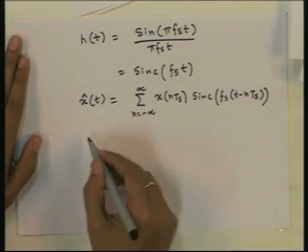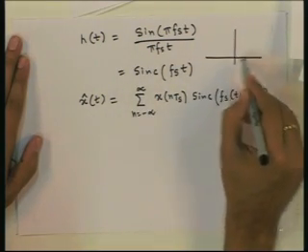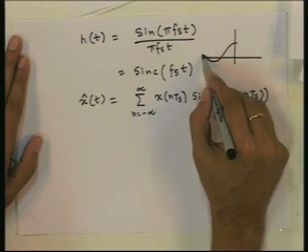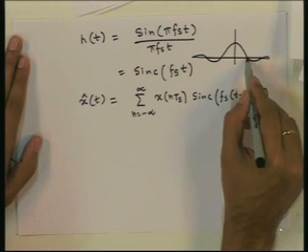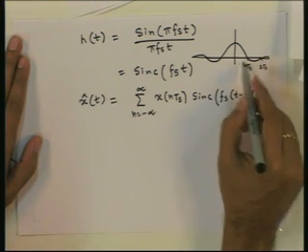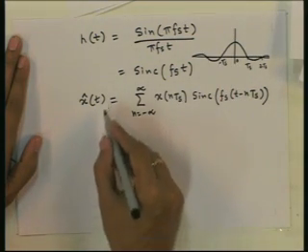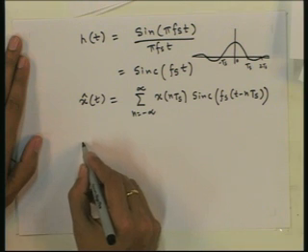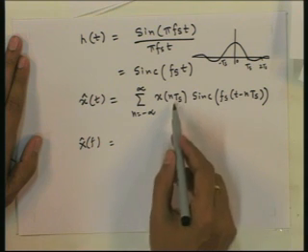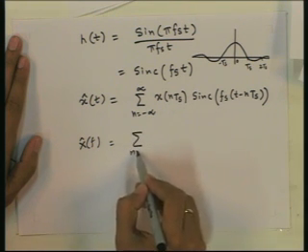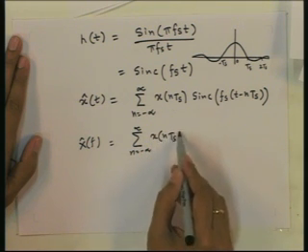Now, consider the Fourier transform of this. Here we have taken a particular impulse response whose shape is like this. This is Ts, this is 2 Ts, 0, minus Ts, and so on. If we take the Fourier transform of this, what is it? X hat f is, this is just a constant, summation n equal to minus infinity to infinity x n Ts.